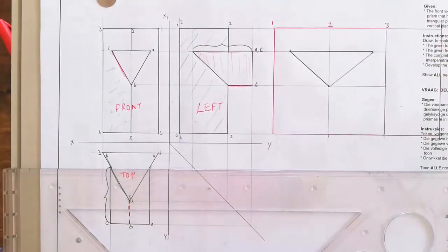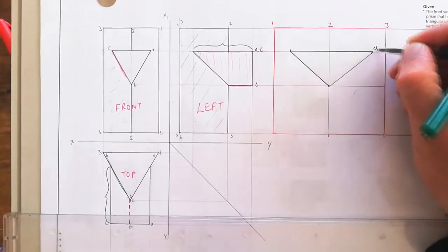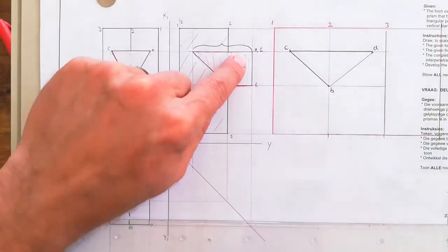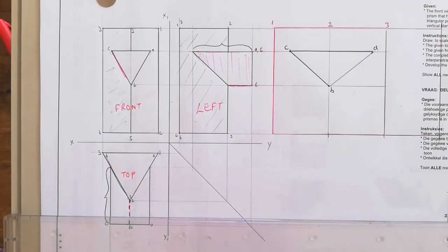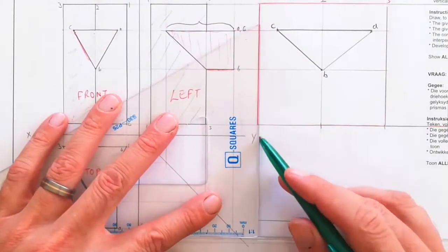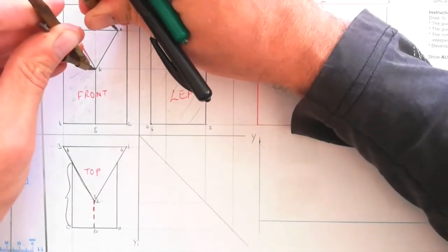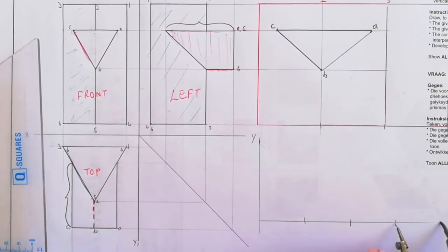That is our main pipe, and just to make sure you are with me, we're going to call this one A, this here is B and C. It's that A, B and C. Okay, for our branch pipe, we can just start off a new drawing at the bottom. We'll just go construction line. We'll give it a 90-degree corner, and we're going to take this smaller triangle now. We can use its true lengths again to have the different sizes. 1, 2, 3, 4. There it is.